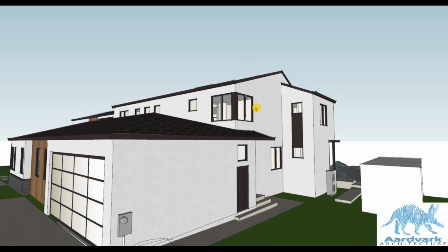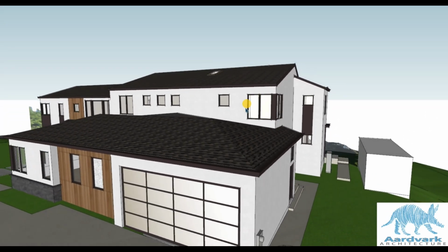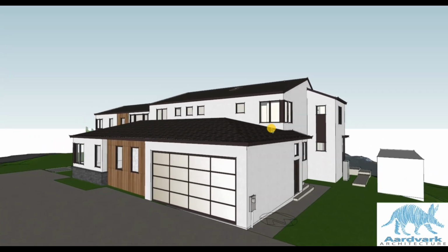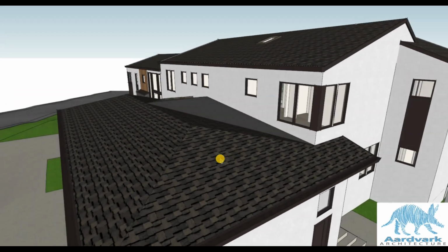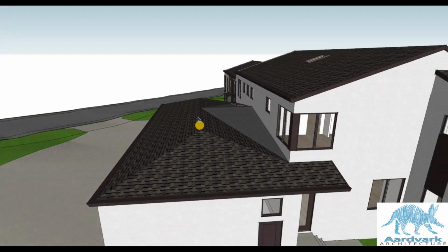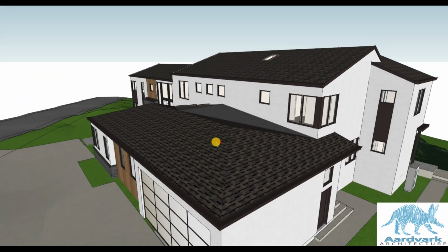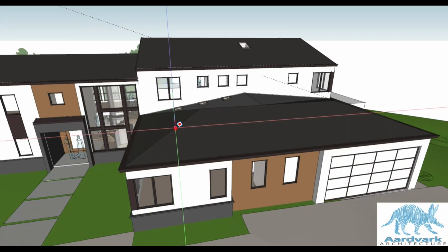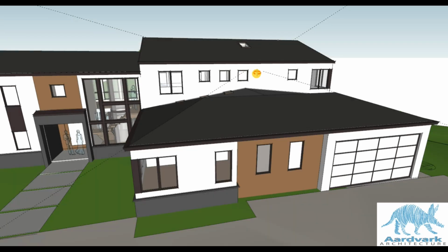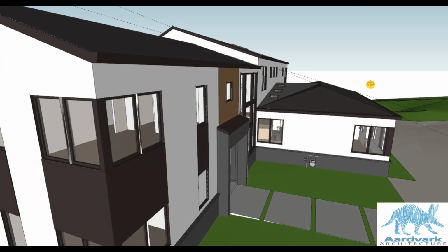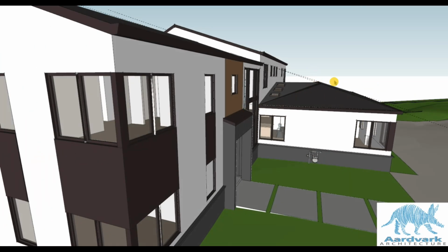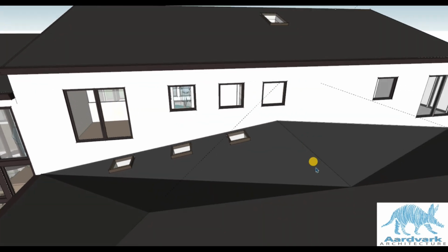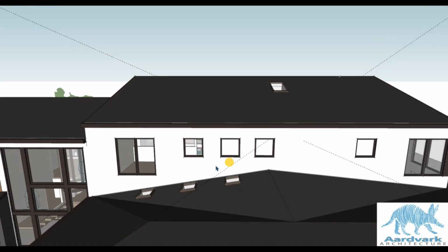Now we're seeing the corner windows for the other bedroom here at the corner. And now that we're coming around the side here, I want to point out that this roof design is pretty nice. Instead of taking these roof lines all the way up to the back wall and having this ultra tall bit of roofing, I'm opting to cut that roof in half, build a hip roof over the garage, and then build this cricket area here that sheds the water away.